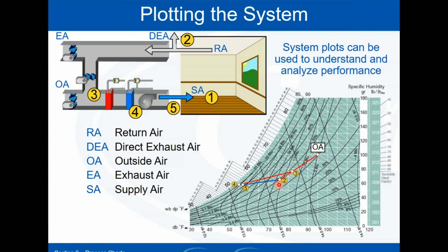Because let's say my room is 75 degrees, but maybe my return air is 78 or 80 degrees or something like that. So in this example, they are showing 75 room air, and let's call it, I don't know, 77 return air. Because the heat of the room is going to rise, the return in this case is up towards the ceiling, so it's going to be slightly warmer than the space condition, right? Then also, depending on where my ducting system is, it might even increase from there.